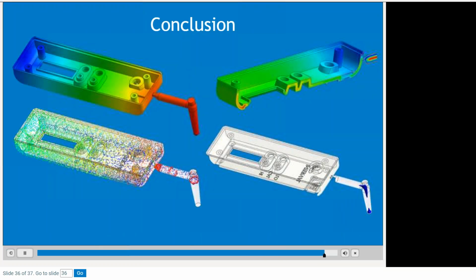As we saw in this lesson, low pack pressure profiles have the smallest volumetric shrinkage ranges, but on the other hand, they can result in sink marks, voids, and other possible surface imperfections. Finding the right balance is key. By optimizing the process parameters, all other quality criteria can be optimized as well.